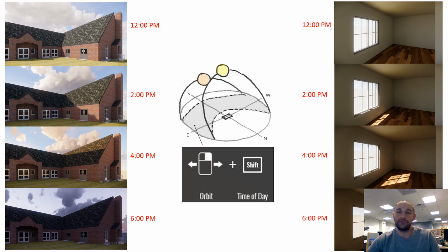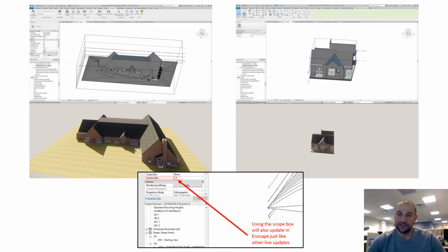and clicking the right mouse button and dragging it left or right, or dragging it across the screen, you'll change the time of day. And you can see the path of the sun as it will chart around the building. If your building is oriented correctly, you're going to have the actual shadows and solar array of the actual site. So it's one more reason to orient your project in the right direction in Revit, and it will give you really compelling shadows and imagery for your light studies.